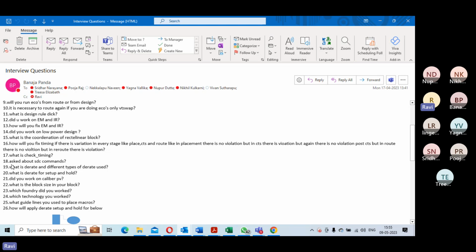Mostly when we are talking about across die or across multiple wafers, you have them characterized. But within the chip, you need derates because you have to look at IR drop variations, chemical mechanical polishing, and various reasons why different cells will have slightly varying differences, which you will model using derate.